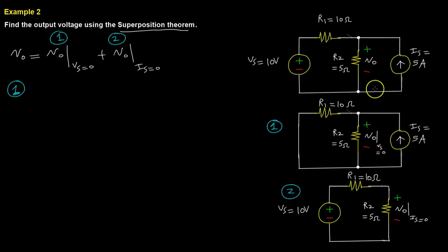So the first case, let's look at it. What would the output voltage be? Well, we know when the 5 amps flows up here, it can only go through these two resistors. For the resistor which V out develops across, we are given the polarity, the passive sign convention, and so this polarity assumes that the current flows down through R2. I'm simply going to do the same sort of logical assumption here and assume that the current is going to flow here and cause a voltage drop.